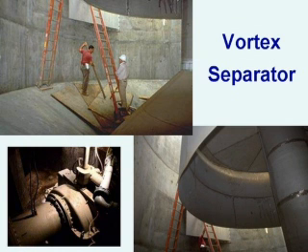It's easy to maintain. The upstream of that bar screen includes a crane above it and a big opening, because what happens so often is you get materials in a combined sewer system that can cause all kinds of problems. When this facility first started, we had tree trunks that actually came down the system that caused the bar screen to torque out, and that became then a sediment pit, and it had to be dug out to get it back in operation.